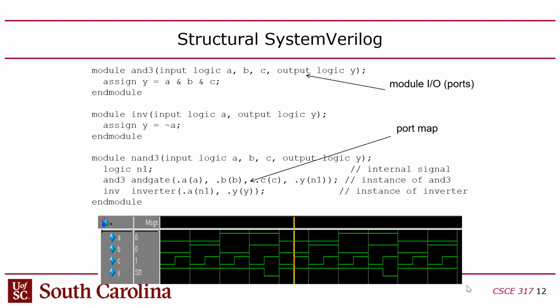Well, who's going to do that? Well, it's either a test bench or it's just going to be the Nios processor. But if you want to use the Nios processor, you can't simulate. You have to run it on the board. The only way to test this, not through the simulator then, is going to be through JTAG. It's going to be through Signal Tap. Does it make sense? You guys with me on this?